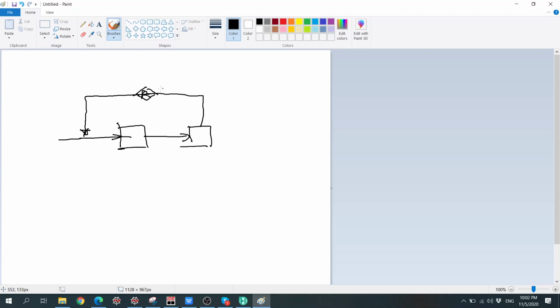So we do the streams, 1, 2, and then 3 and then 4, and then here you put like 5 for example, or 4 recycle, and we have done until stream 4. The stream 4 will then calculate for us the temperature and pressure and flow rates. And then stream 5 is the recycle, the stream that's going to be mixed with stream number 1 to make stream number 2.